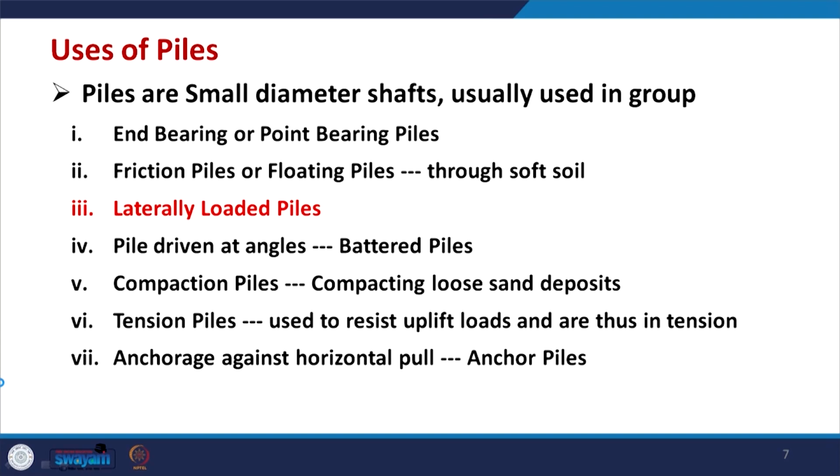But there may be cases when the piles are passing through loose sand or soft clay, where you may not get the end bearing or point bearing action. Then what are called friction piles or floating piles are used through the soft soil or loose soil.